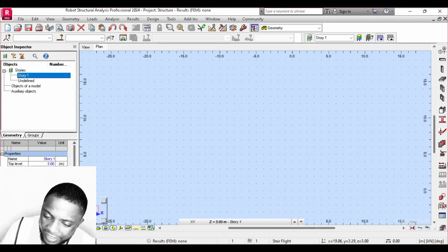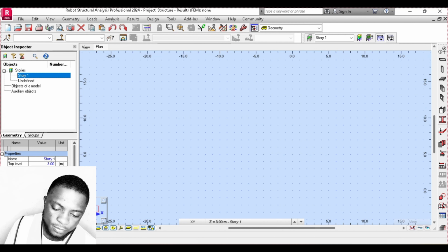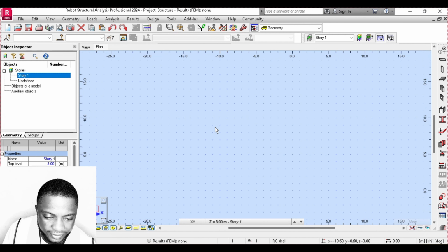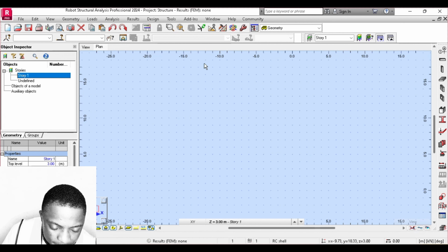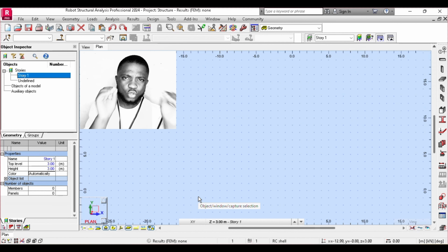On the right side of your screen, you have your axis definition. Then you have your structural elements such as your beams, your columns, your floors, your walls, your openings, core walls, and your member section, which is important in defining your column sections and beam sections. And finally, the center, which is your model space. Think of it like your drafting table. You don't need to memorize everything. Just know where to click.